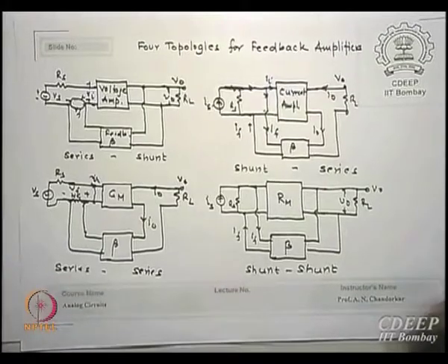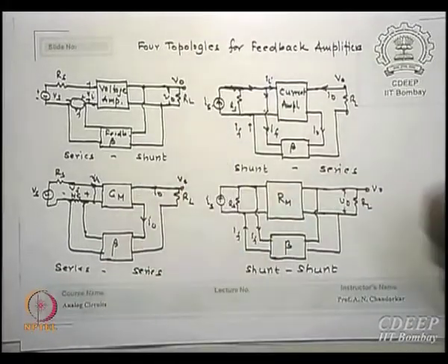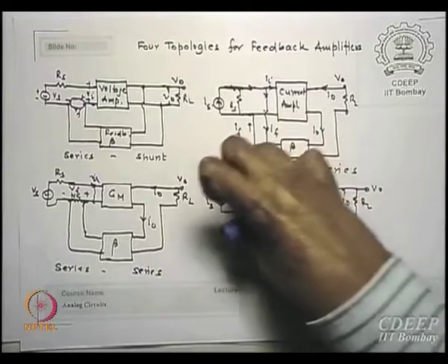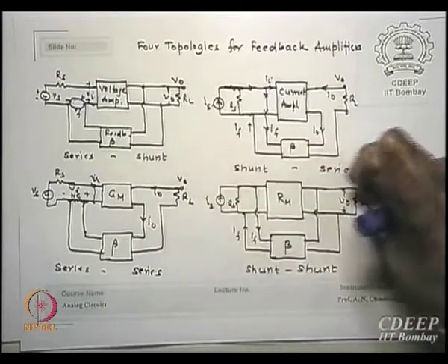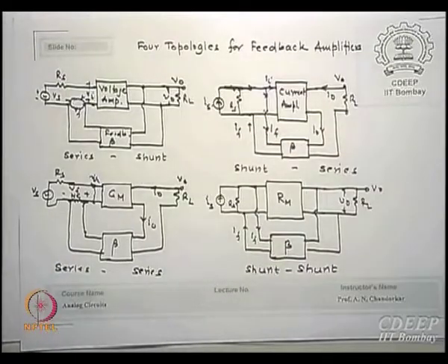By the same logic, both sides are shunts. This is voltage, this is current. Voltage divided by current is resistance. So these shunt-shunt amplifiers are essentially called transresistance amplifiers, is that correct? So feedback allows you to create 4 possible amplifiers.